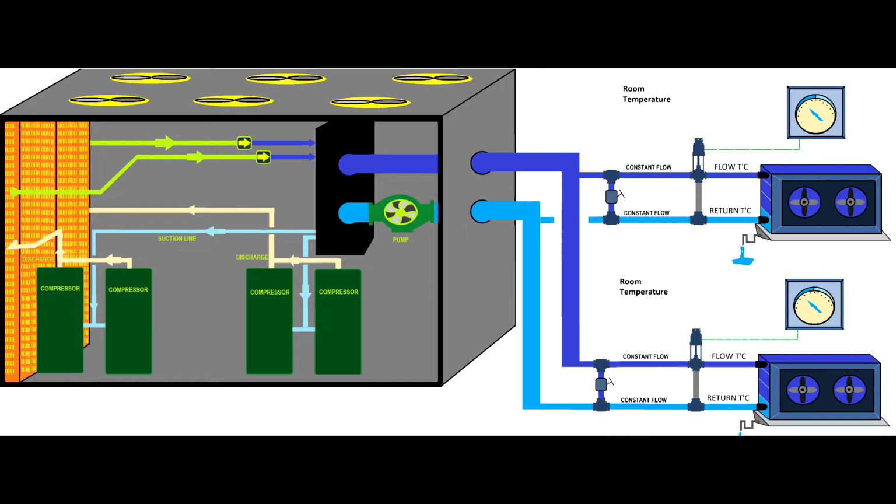If the water is not cold enough, then you will not have condensation on the heat exchanger, and then you might have temperature control problems or dehumidification control problems. And I suggest that you go and have a look to see what happened with the chiller, with the main cooling device.